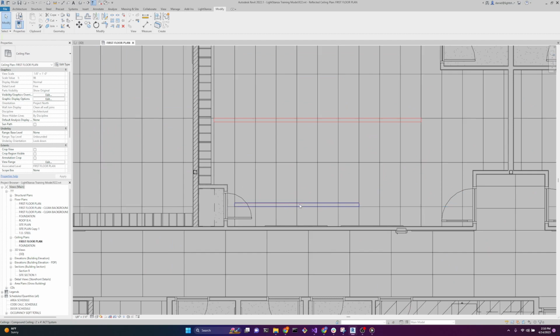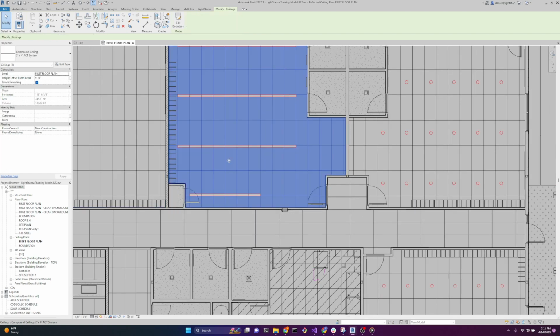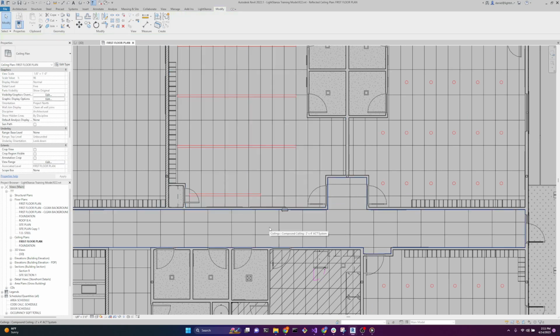And so the reason why you want to set this equal to your custom length parameter is so that you can keep the IES file center position the same as you change the length of the parameter. And also, in scheduling, you can use the same custom length parameter. You don't have to have two parameters. And so that's why you want to do that. There's also a video on the other two parameters we have in Revit for the proration and scaling of IES files. You can refer to that video for information on that.